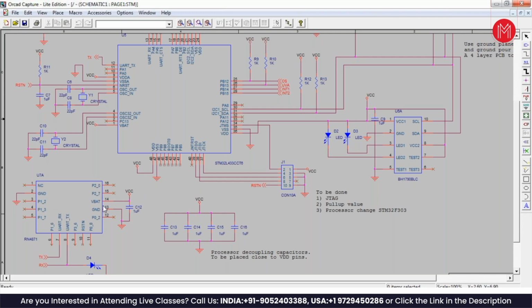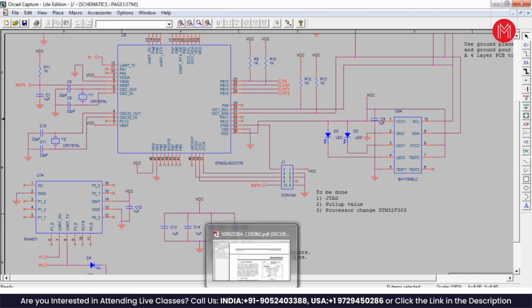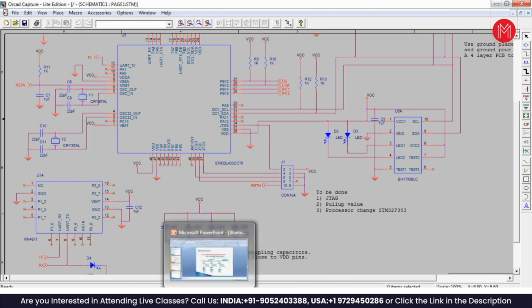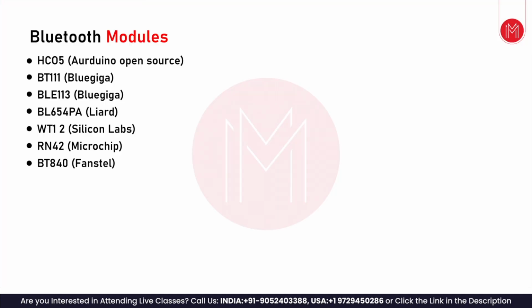You can use the GPIO pins, then through the UART interface you can control them. Typically it will have an API or something through which you can configure the GPIO pins, set values on the GPIOs and all. That's the GPIO that we are talking about in the block diagram in the PowerPoint presentation. These pins, GPIO pins. Typically, all Bluetooth modules will have spare GPIO pins that can be used for that purpose.